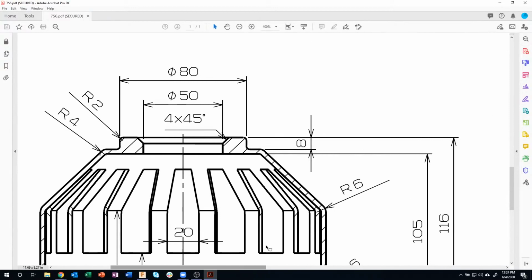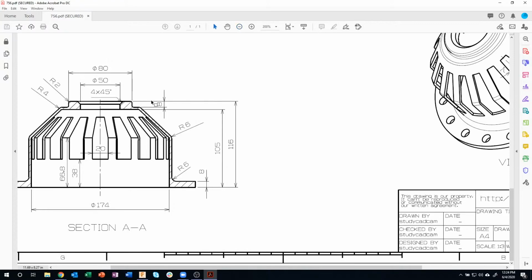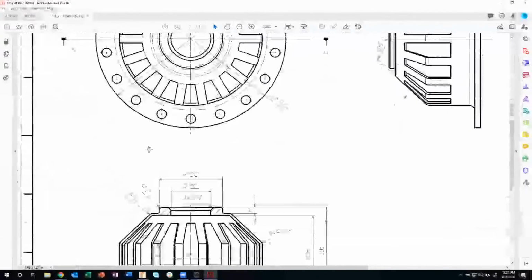It might be a little hard to see, but it's also probably curved on the inside. So if the outside is curved and then I specify my wall thickness, it'll actually bring that fillet onto the inside also. So in this example, I want to add my defining fillets first.